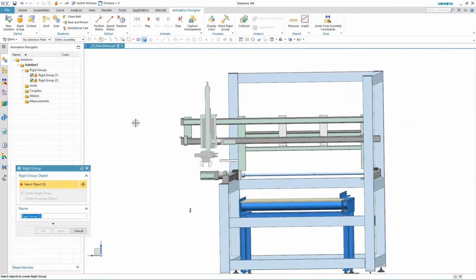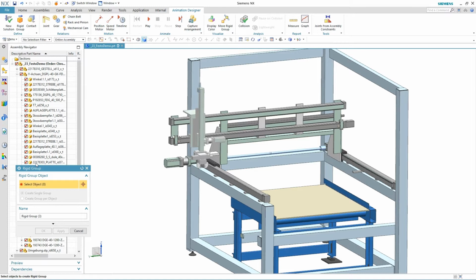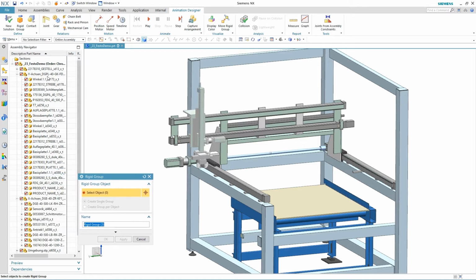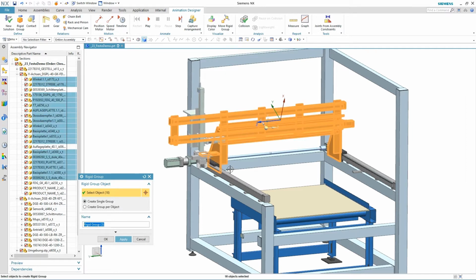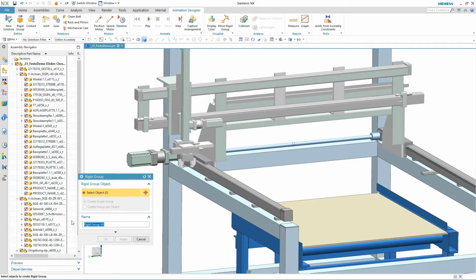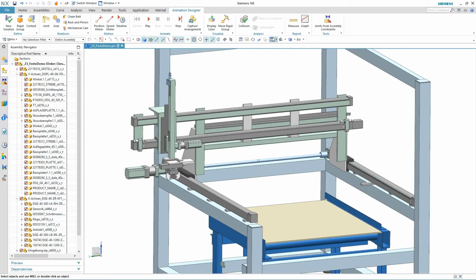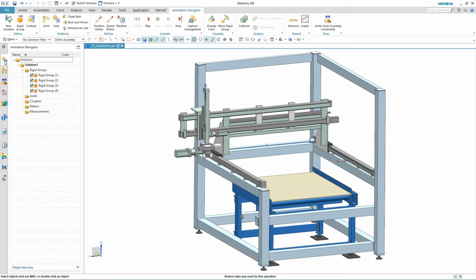We can select components directly or by rectangle select. Watch as we freely choose components without having to adhere to any assembly structure rules, giving us total flexibility in moving whatever we want. We can also choose complete subassemblies using the assembly navigator. This subtle yet important detail here is that you can move any component regardless of where it lives in the assembly structure. Notice how we'll move the small slider supports that are buried deep in some subassembly.